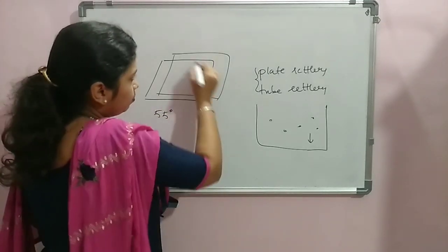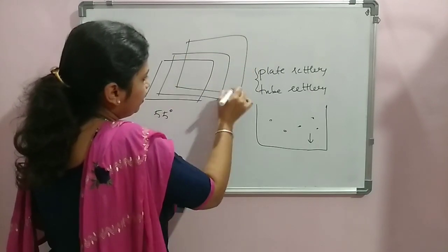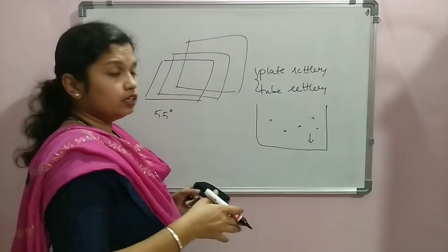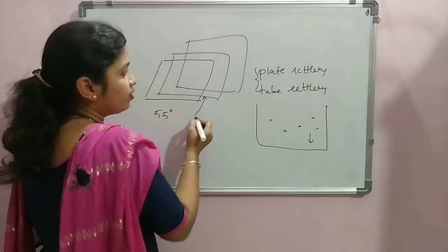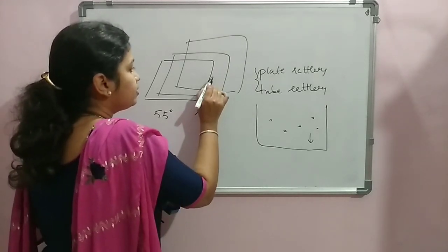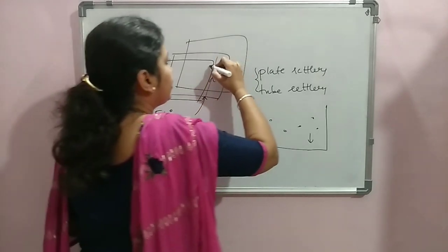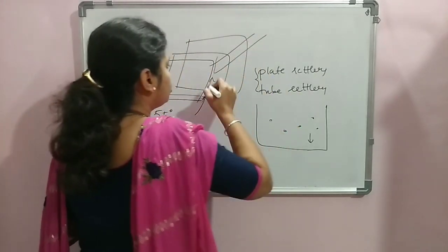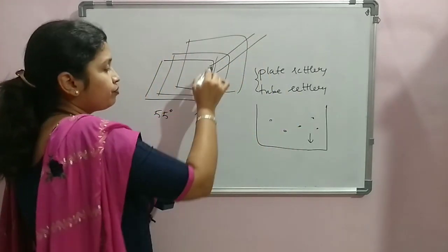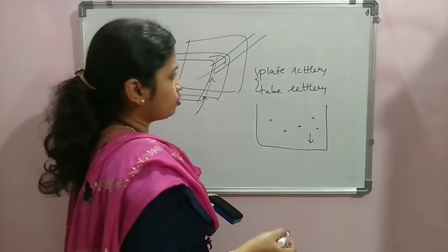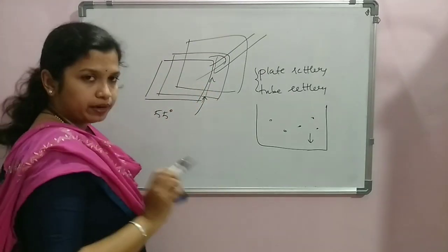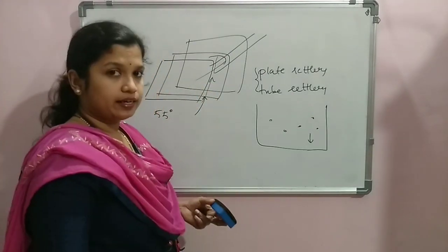This arrangement of plates is placed inside the tank. Water is made to rise through the bottom orifices which are provided. It rises up and is collected by the common collection channels connected to the plates, and from here it is taken out for the next process. This is the case of plate settlers, which will be studied in detail further.